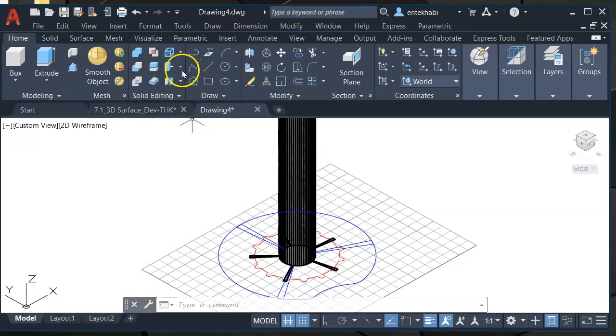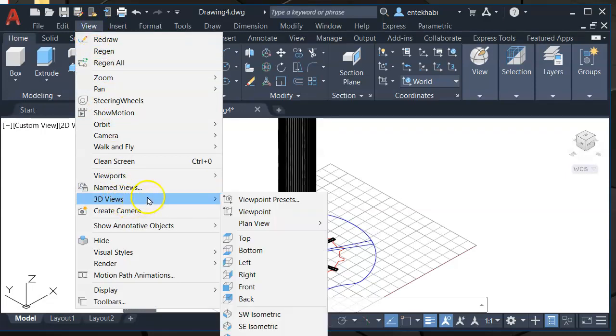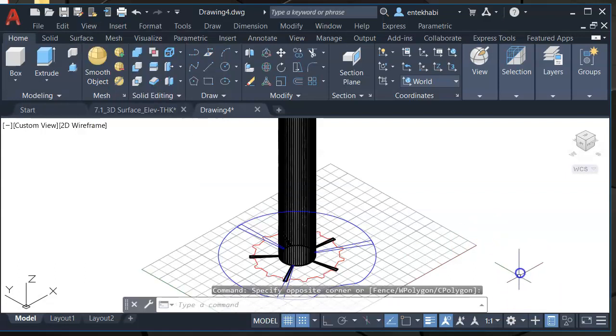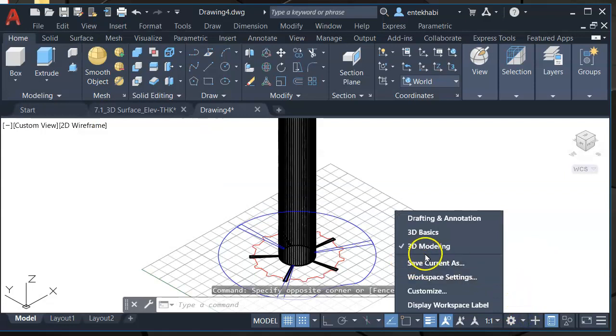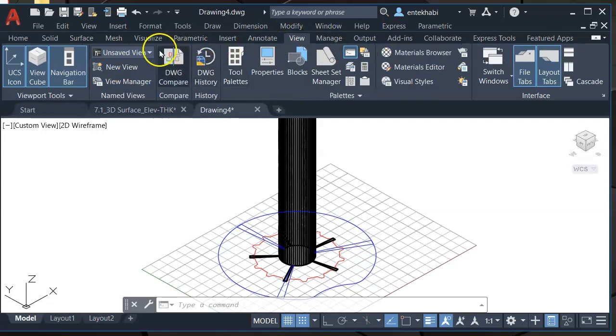Now we can access the view tool both ways, from the top pull-down menu and also from the pull-down menu that comes with this ribbon on the 3D workspace. We switch to southeast isometric. Default is southwest, the way you're seeing right now. Notice that X and Y and Z orientation. This is southwest, and I like to switch to southeast as the best way to view this. So our front view always is going to be XY.